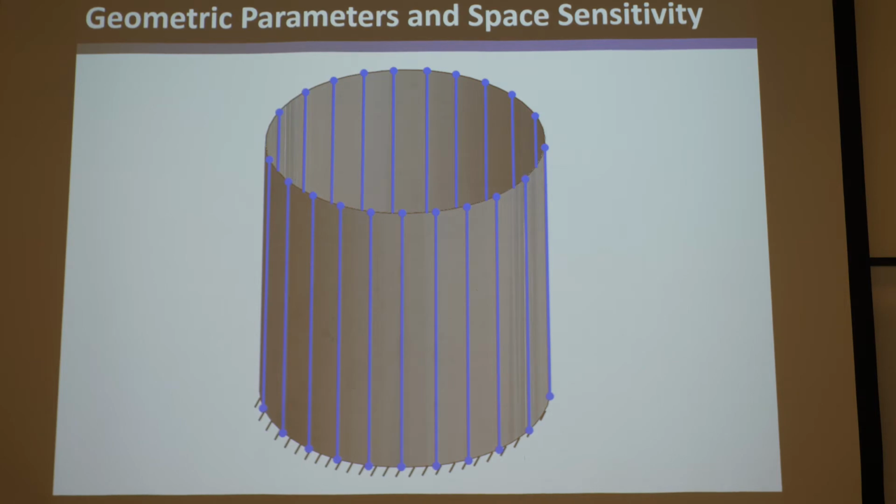The nice thing I do like about modal analysis, degrees of freedom, is it takes reality into account, removes all the idealized stuff, and you can actually start rank ordering your natural frequencies and mode shapes. But again, where do you decide to cut off what things are degrees of freedom, what things are constrained? At that point, it is not clear. So there's a lot of ambiguity in all the definitions of degrees of freedom. But I think fact is the least ambiguous and the most clear because it's all idealized. But again, it's not going to mimic reality all the time.